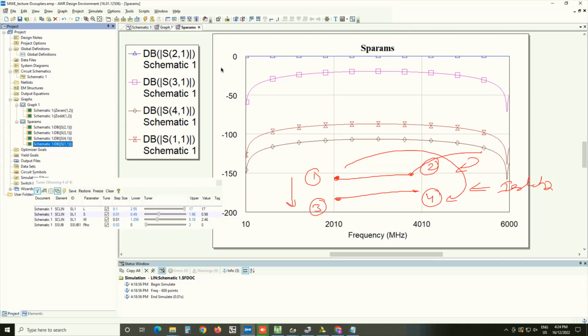So this difference between coupling and isolation gives you a number called directivity, which basically tells you how good this directional coupler is at separating the two kinds of waves, the incident wave and the reflected wave. Remember that if isolation was only 40 dB and coupling was 20 dB, the signal you are trying to measure is 1/100th of the actual signal, and the interfering signal is 1/10,000th of the signal you are trying to measure. So that's okay, because that's like 1% interference.